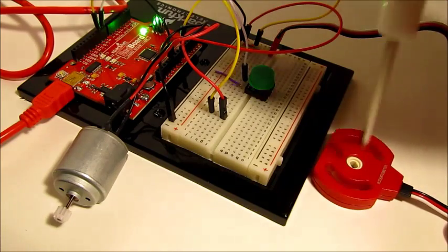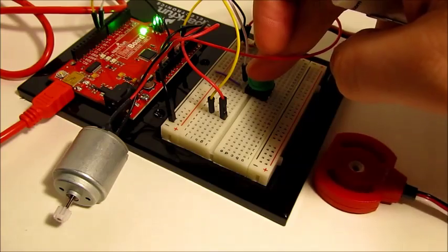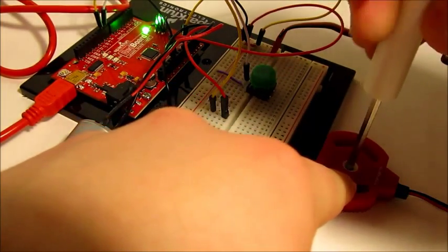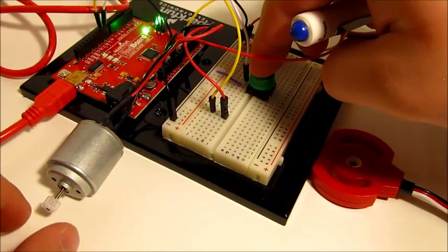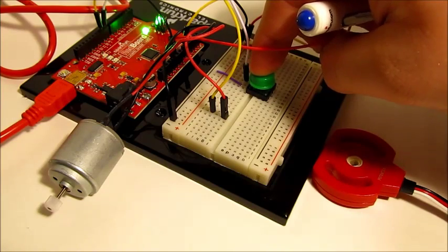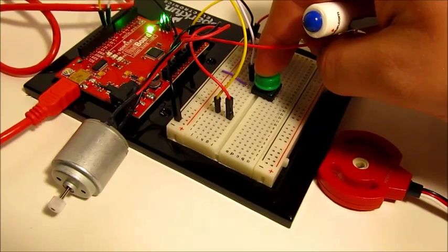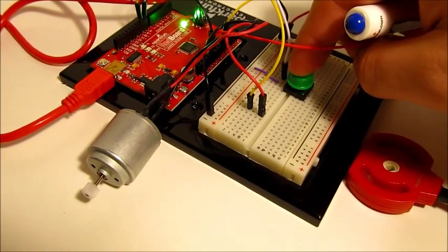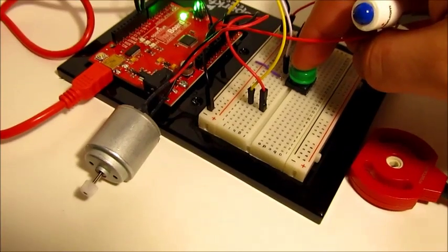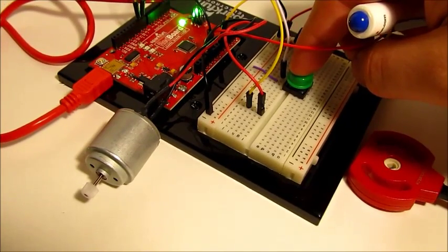In the case where we have the potentiometer turned all the way up and push the button, we give the motor a little kick, and it comes on. We have to give the motor a little bit of a kick because the current coming through the Arduino is not enough to get past the stall current to get the motor initially moving. Unfortunately, I don't have my battery with me right now, otherwise I would be able to run that without giving it a kick to start it.